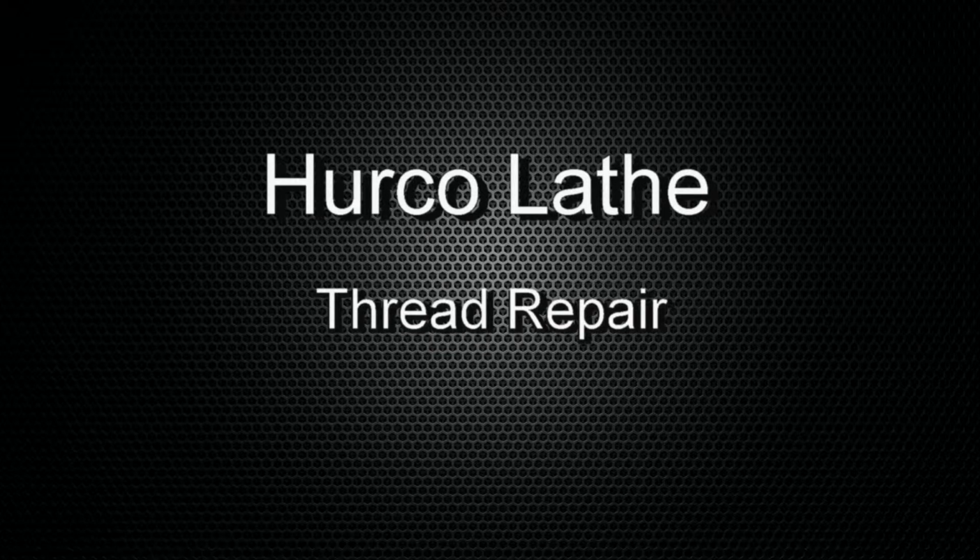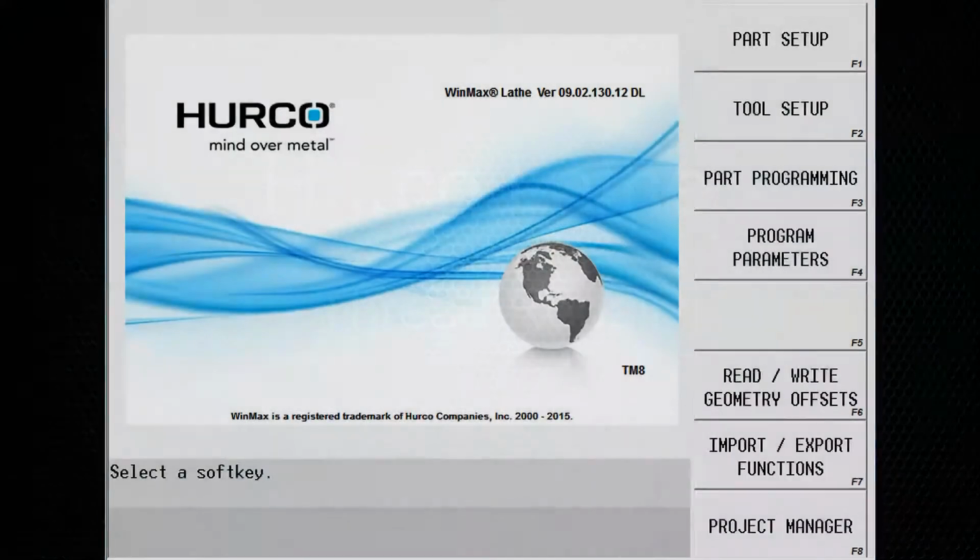This is the thread repair setup on Hurco lathes. Before beginning, first turn on the machine and press power to enable the axes. Calibrate the machine by pressing the Calibrate Machine soft key and cycle start. Once the machine is fully calibrated, press the input button on the control to get to the home screen.